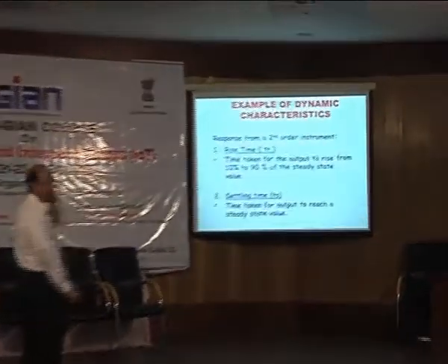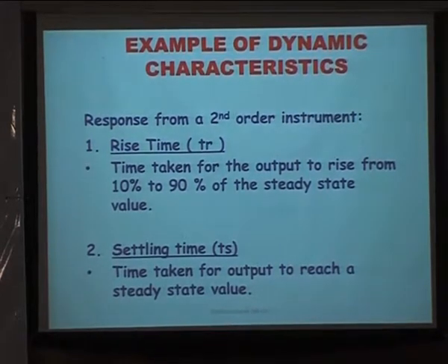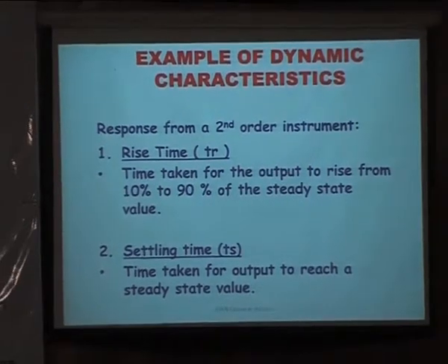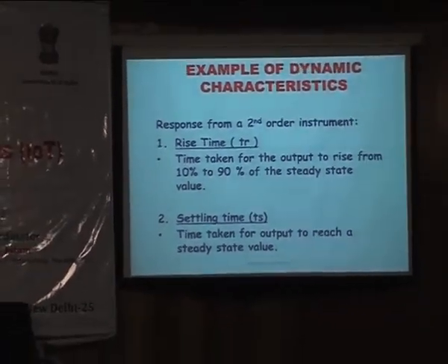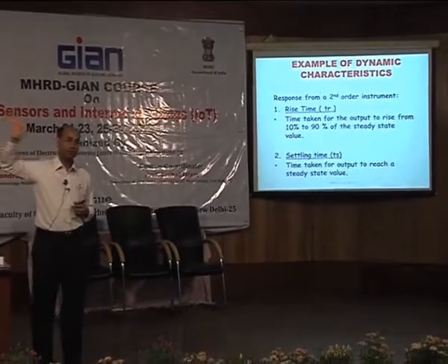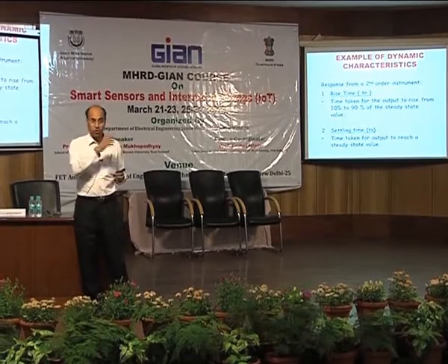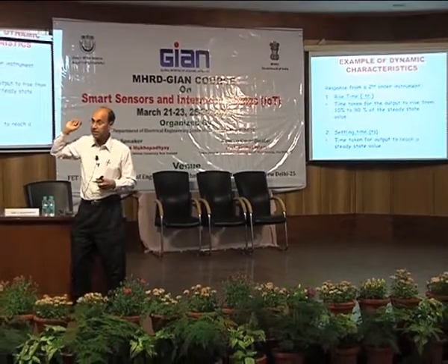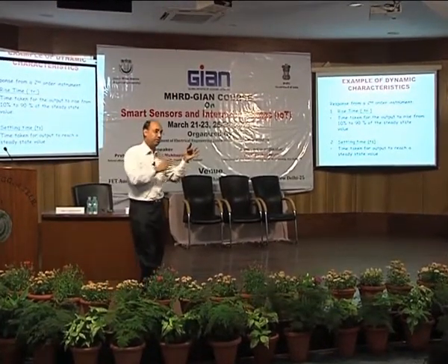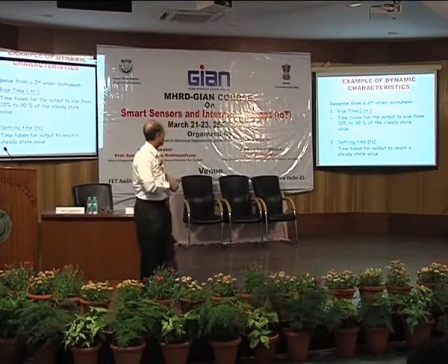But in a second order system, there are a few more terms, not only the time constant. Time constant is not applicable here, but rather we define a few other terms. So one is the rise time, usually measured between 10% to 90% of the response. And then we measure settling time, which is within either a 5% band or 2% band or 1% band. So they are related to delta omega n. Okay? So you will have delta omega n. Like if you think of settling time based on 5%, you will have 3 by delta omega n. So like that they use.